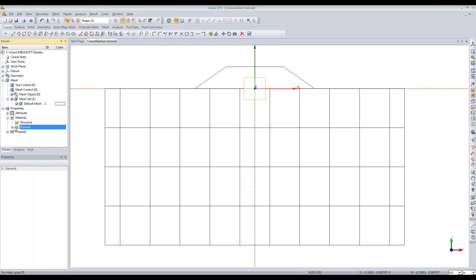Okay. Now that I have my ground material properties defined, the next thing I need to do is create my meshing. So let me see if I can set this up here. All right, in our previous example, we meshed a 3D model, or a block. But with this particular project, we have 2D or planar elements, so we have to use a different meshing option. Just go to Mesh, then go to Auto Mesh. Oops, wait a second, let me change the settings here.